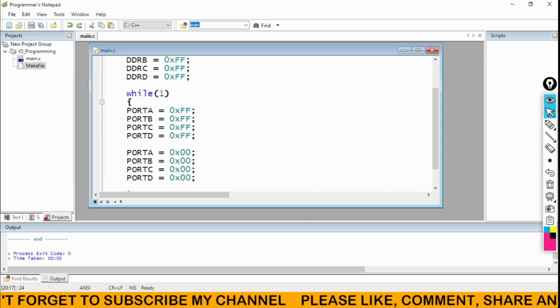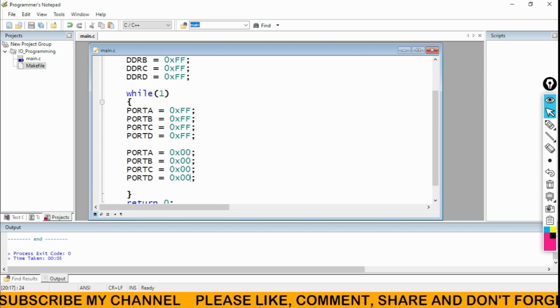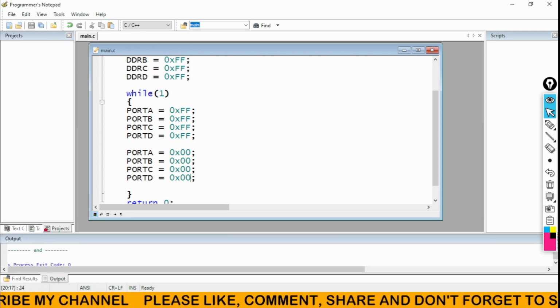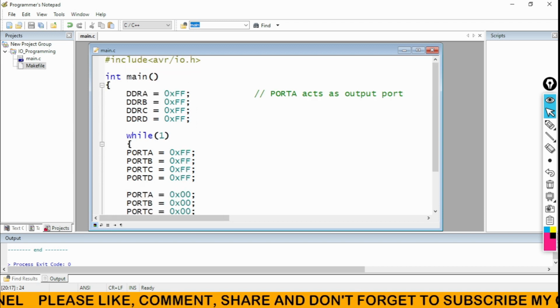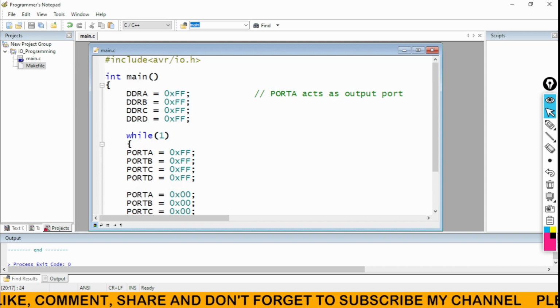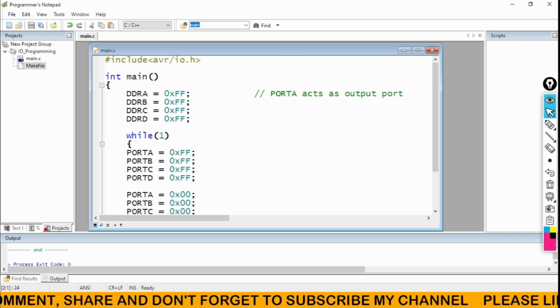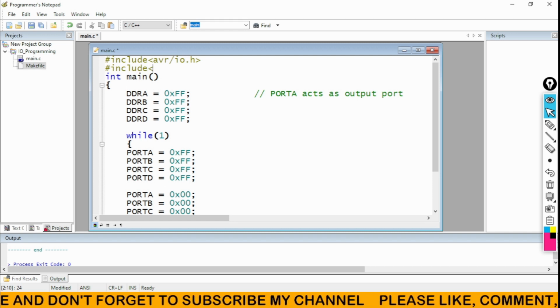But if we write like this, port A all high, and then again port 0, all low, it will not blink visibly like this. So for that purpose, we need to add some delay.